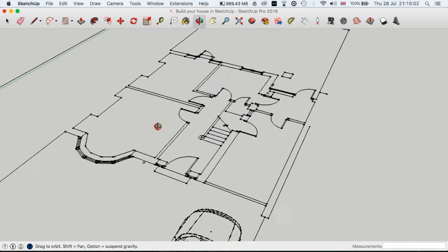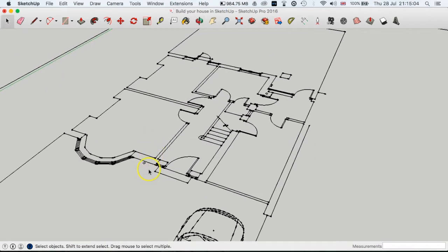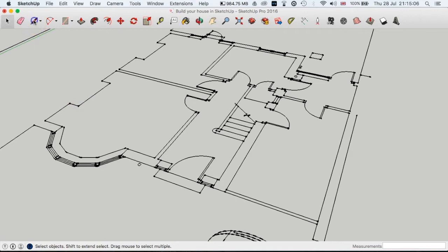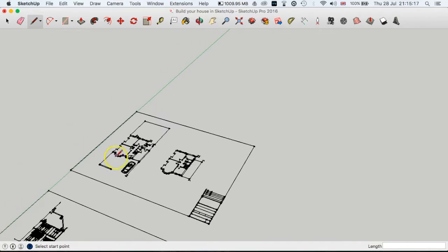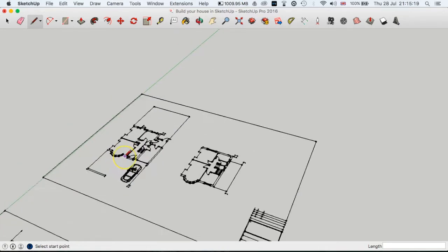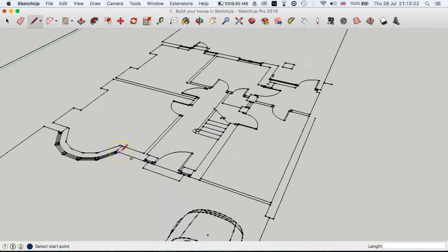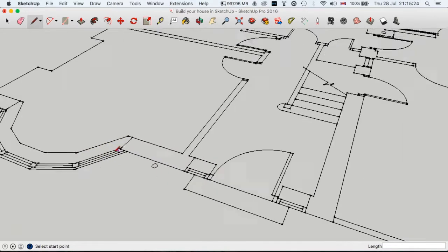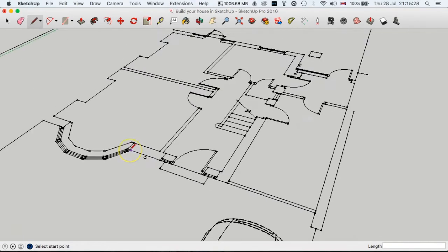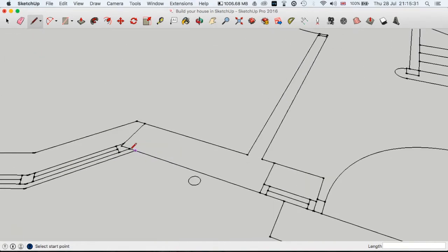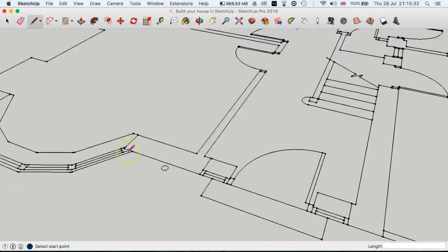as you can see. Now, if you've got the plans already, it's great, because what you do is draw over the walls, etc., and then take them up. Now, I know what you're saying: well, I don't have plans, I need to start from scratch. Well, this is where you make your own plans using SketchUp. What you need is at least a tape measure, but a digital tape measure, a Disto, is also a good one, because that makes it a lot more accurate, and you can do it very accurately to the nearest millimeter.